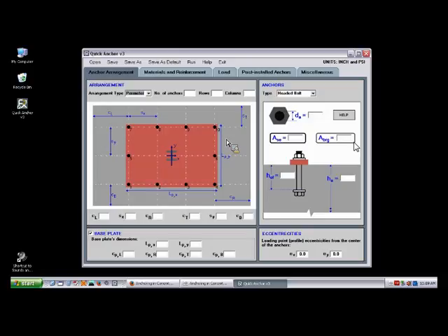And for tension analysis using Appendix D, the anchors that are in tension, only those anchors are included in the analysis using Appendix D provision. Now, this is also another new feature in version 3. In the lower versions, you had to do this job yourself and input only those anchors that are in tension. But in version 3, you don't have to do that anymore. You just input your whole anchor arrangement, and then you will input all the loads, and I will go over that, the load input part, very shortly. And the program does the rest.